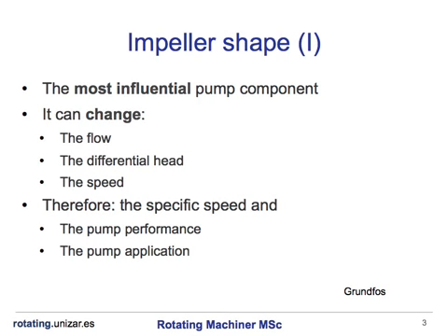The impeller is the pump component that has the most influence on the pump performance. Actually, you can create a brand new pump by just modifying the impeller. It can change the flow, the differential head, the speed, therefore the specific speed, and the pump performance and the pump application.